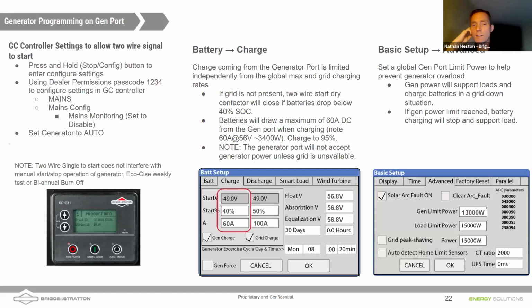So let's use the example where we can do 10 kilowatts of charging, right, for a 20 kilowatt hour stack. Well, it would take 2 hours to fully charge up a stack from 0 to 100%. Now, typically, you're not going to be all the way down at 0, right? You're going to start your generator when your batteries are at 30%. So going from 30 to 100% is about 14 kilowatt hours of energy.